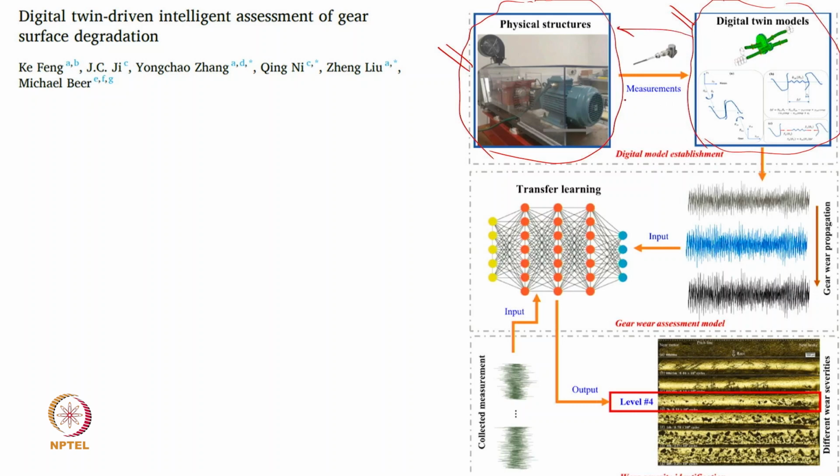After that, through sensors, we are able to measure the data, and we are giving those measured data to the digital twin so they refine it. After that, we can also utilize simulated data to go for the future prediction, and those simulated data can be analyzed using ANN. In this case, what we use is transferring a knowledge, and that knowledge also can be corrected when we are having data from the physical system and can be compared with this.